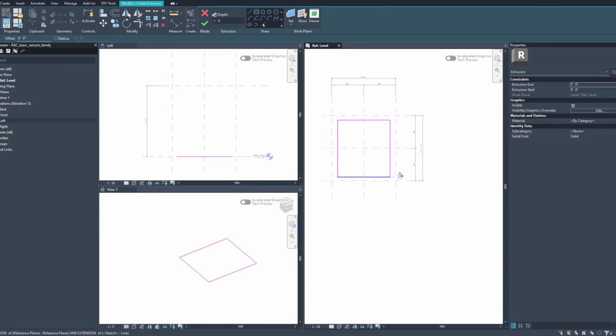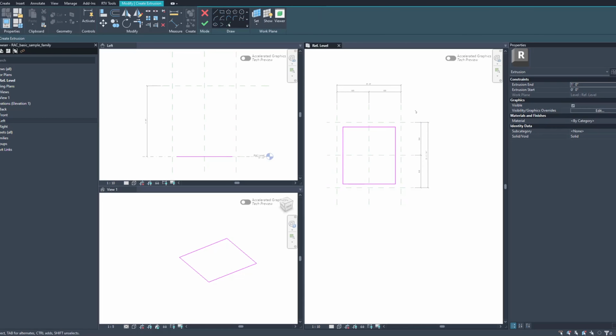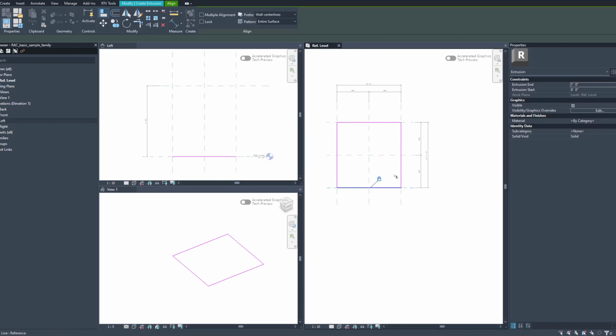All right. Now you see that sketch in all 3 places. Okay. And now what I want you guys to do from an extrusion standpoint, you'll see how we got all this. Now we're going to show a command called align and locking. What that means is we're going to hit AL. We're going to click on the reference plane. Boom. Now I can also do this what we call multiple alignments. I could do that as well too. But this I want to show you right here. Look, and when I click on that, boom, same thing here. All right, same thing. All right, cool.